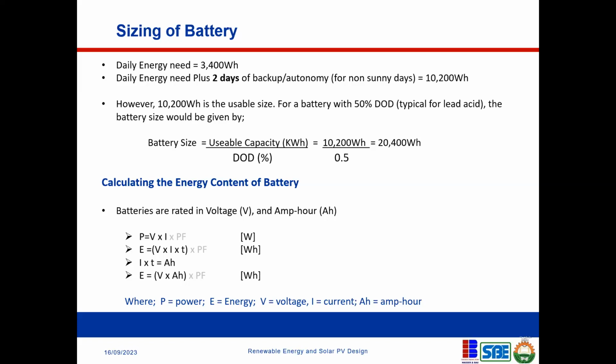That is the energy that they can store. But in some other batteries, you will not see the kilowatt hours. You see voltage, you see current. So you see something like a 12-volt battery, something like 200 amp hour, maybe 24 volt. So depending on the kind of battery you're seeing. So what I want to establish here is how you can calculate the energy that the battery can store when it is not given.